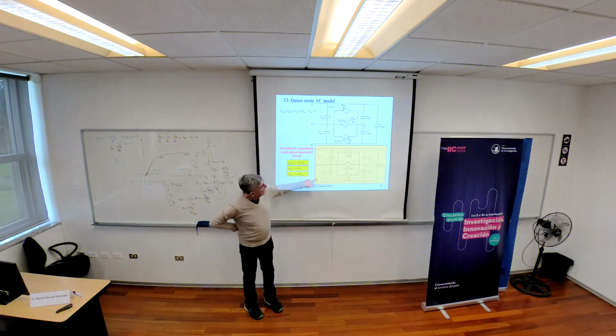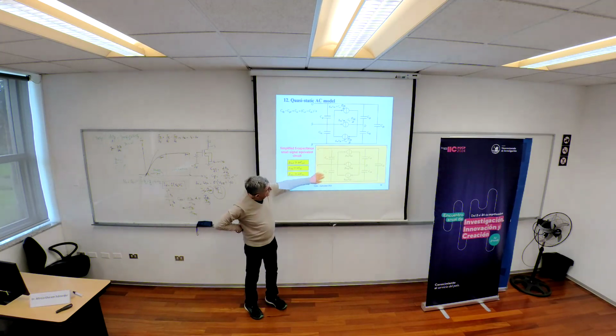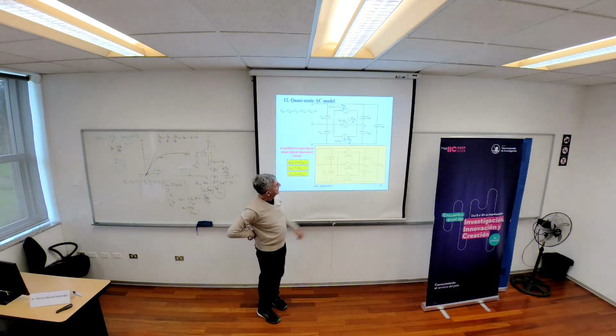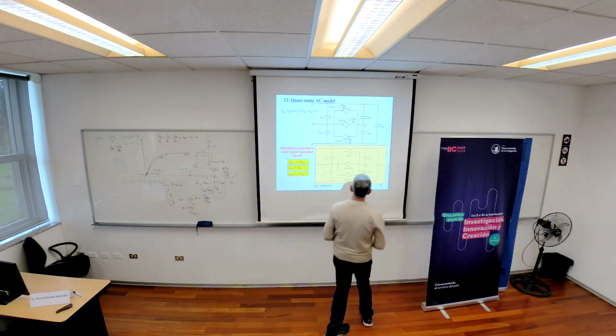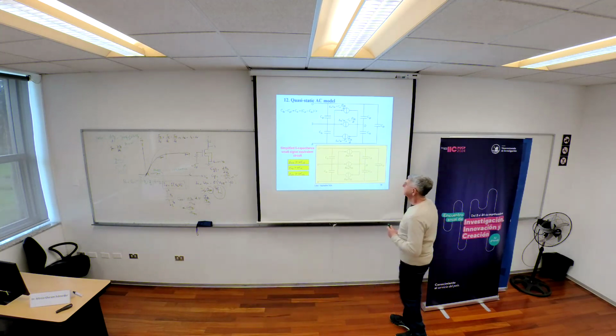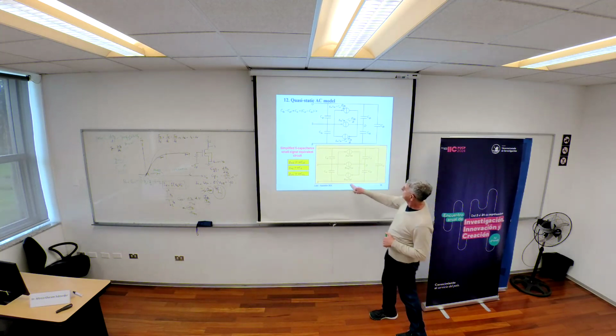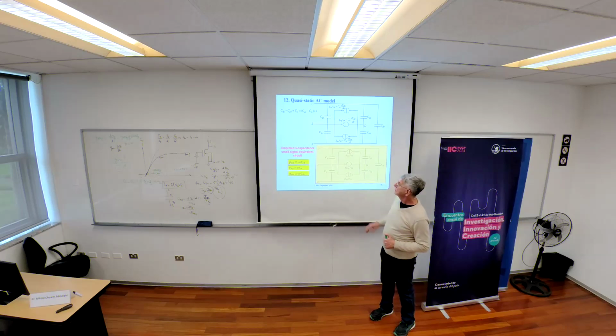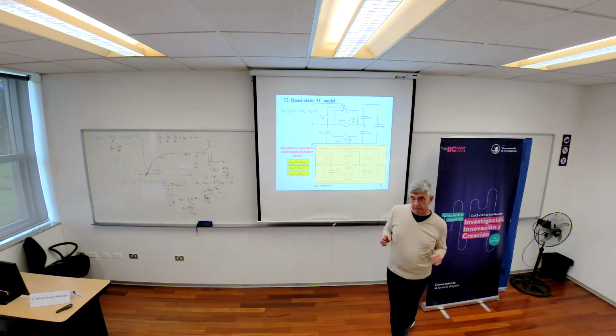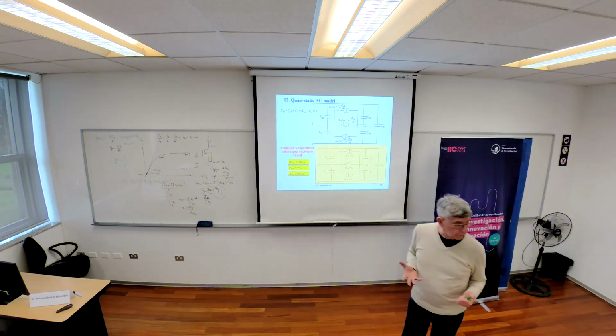Okay. Then you remove this guy here. It doesn't have any effect on the circuit. Okay. What else? This current source here disappears because VSB is equal to 0. So you have a simpler problem to solve.